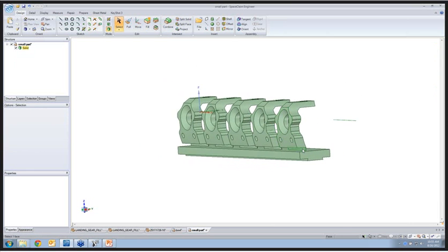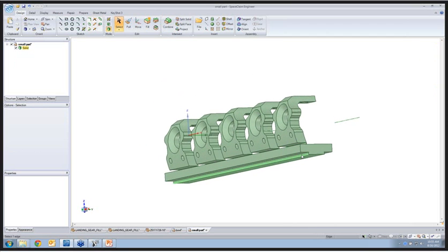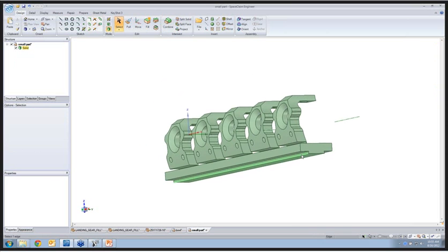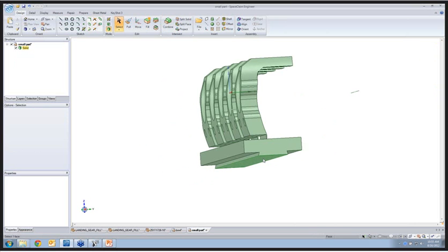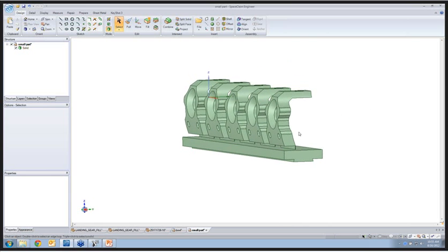When you're done machining these, those generally will snap right off. And the entire fixture, the entire part is held through some other kind of standard fixture off the shelf through these dovetails. So it's a great way to machine things out.